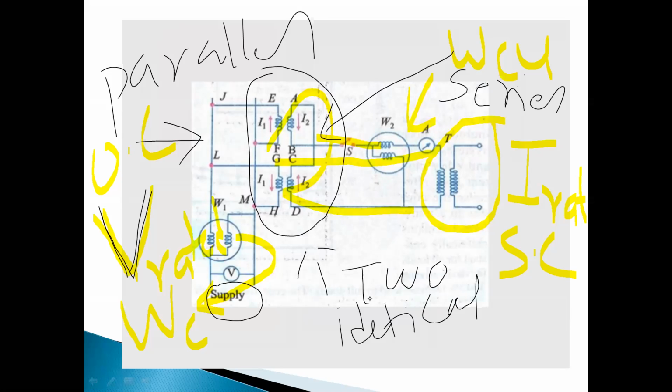Okay, in this manner we calculate the efficiency of the transformers by conducting the Sumpner's test. Temperature rise is measured directly with the help of a thermometer or other temperature measuring equipment. So if you compare this test with the open circuit test and short circuit test, on the primary side we conduct the open circuit test and on the secondary side we conduct the short circuit test, but the two are conducted at the same time. That's all. Do you have any doubts?